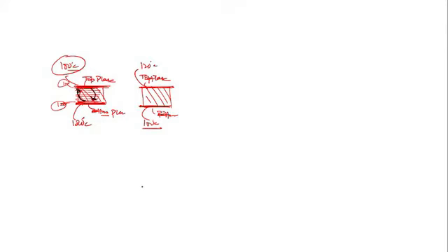That causes the bulk motion, because the fluid adjacent to the bottom plate will have high temperature. Since they are at high temperature, obviously their density will be lowest, and any fluid layer at the top surface is at the lowest temperature of 100, so its density is highest. That will come down and that will go up. That causes current in the fluid. Then in that fluid the heat transfer is via, tell me please. In that fluid the heat transfer is via convection. Yes or no? Q dot convection.